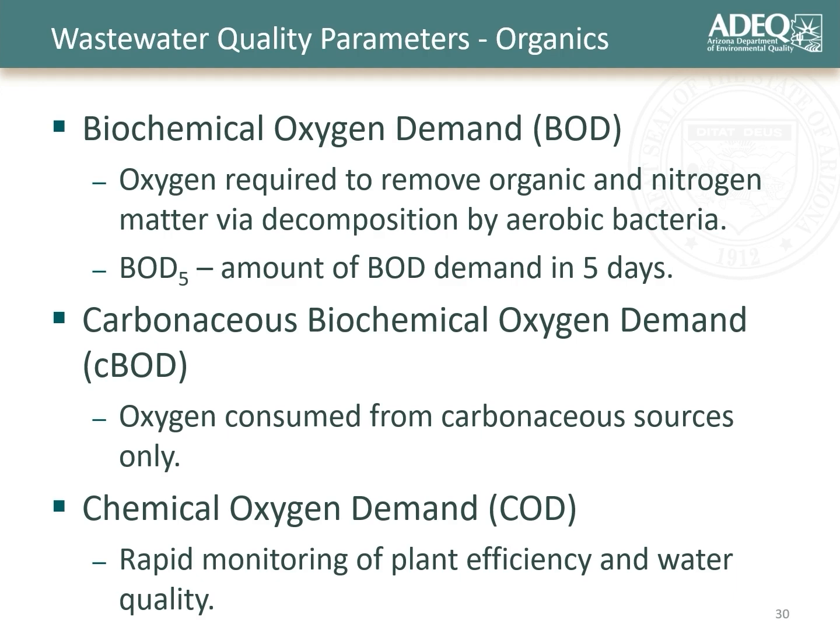So in this particular test, you take a sample and put it into a BOD test, which we'll be talking about a little bit later. You let it sit there for 5 days, and after 5 days, you then measure the amount of oxygen depletion that has happened, and that is the way that you measure your biochemical oxygen demand.